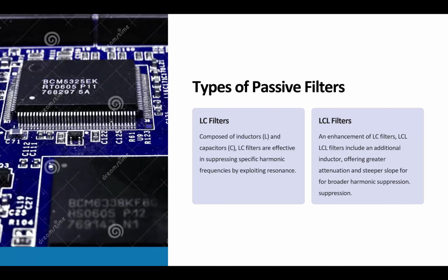Okay, so cost-wise, passive filters are better than active filters. But when we go into the design of the passive filter, we are going to see its limitations. If those are important for us, we have to move on to the active filter. If not, passive is the answer. Normally in power systems, at a low or medium level, like an MV grid or LV grid, low voltage grid or MV grid, they do not go to the active system because it doesn't justify the cost.